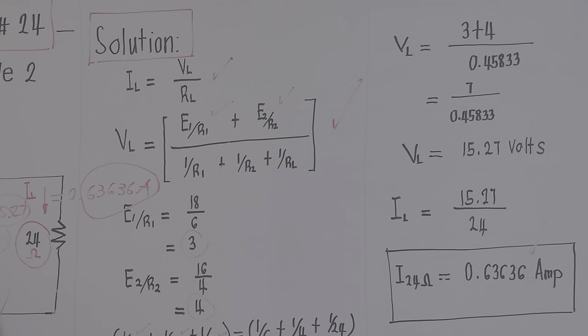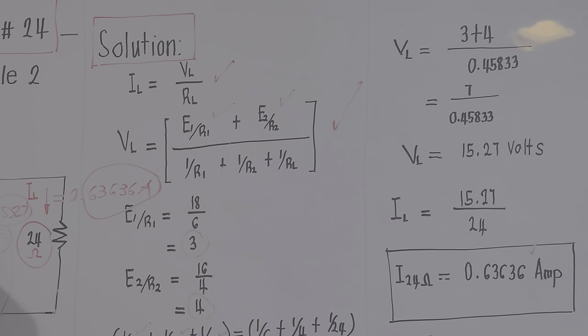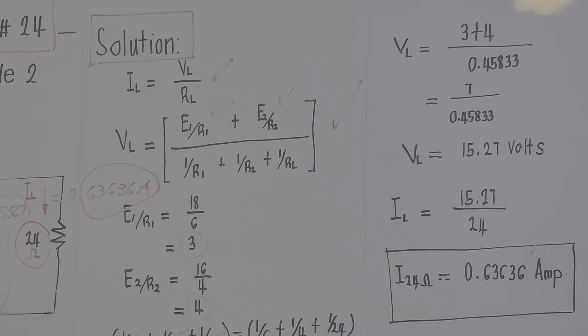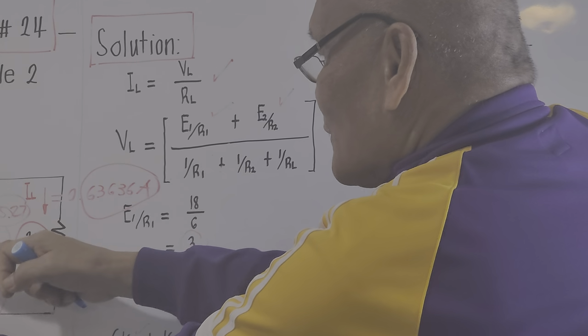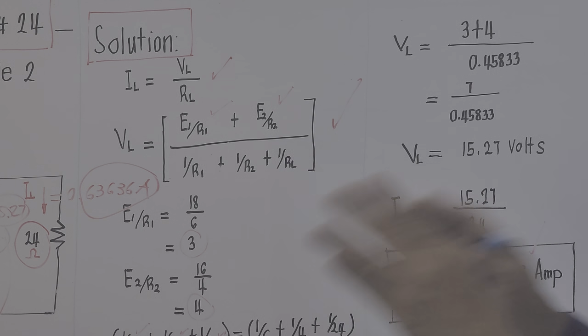Then we could compute the current emanating from this 16 volts over here. Upon the computation of the total current emanating from the 16 volts, the voltage across this portion now will be 16 minus the total current emanating from the 16 volts times 4. And that's V sub L due to the 16 volts here. What will come out will be 8.727 volts. The voltage across this due to the 16 volts is 8.727. I just give you the summary of the computation. I verbally explain it, right?